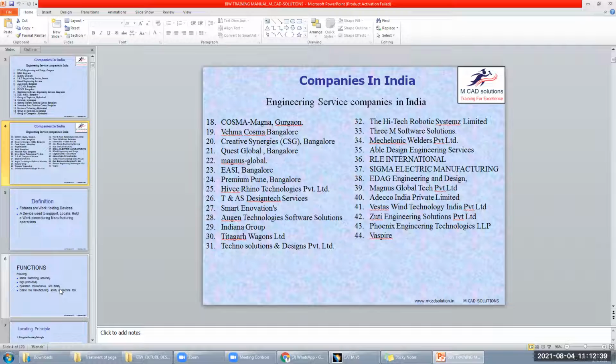So we have to create a linkage mechanism. By using the linkage mechanism, we have to apply the proper force. So project cost will be less, but designer work will be higher. We have to take care of all these things, because in a linkage, if any link is short or there is any problem, it won't work, it will lock. So we have to check for working, for force, and for proper opening angle. So there are more calculations as compared to